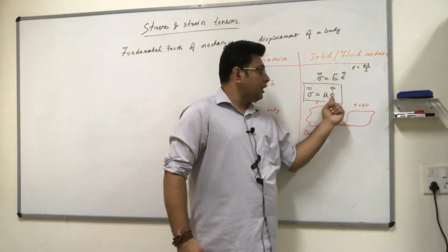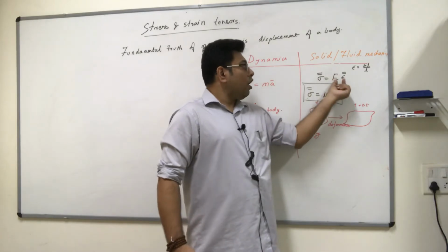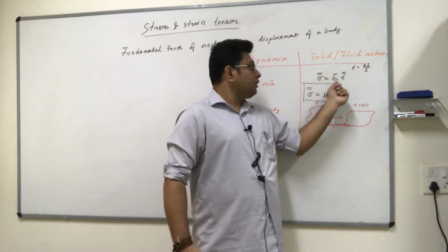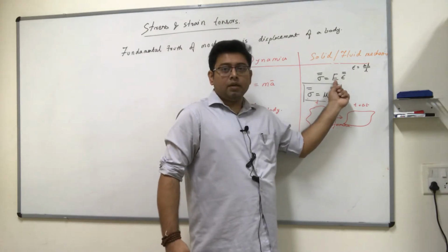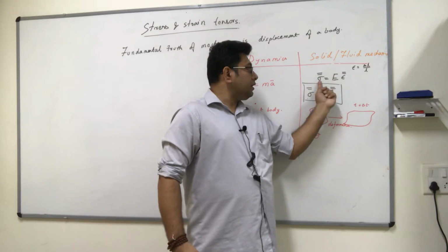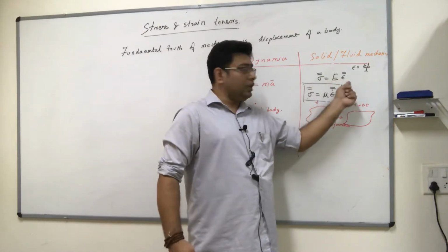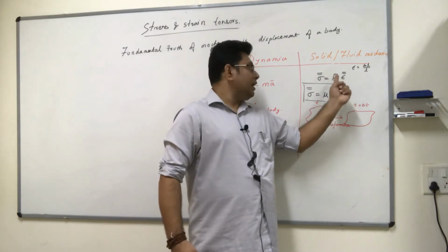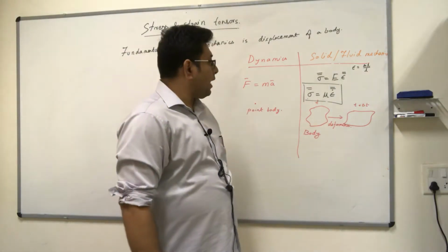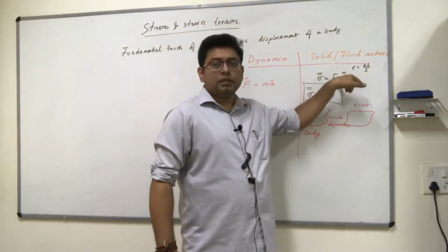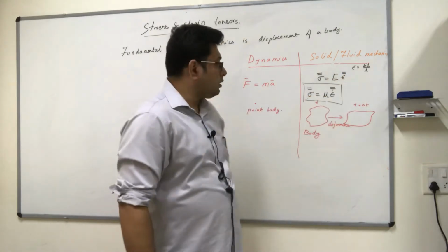And we will see that this actually becomes a tensor. This is also a tensor. In normal solid mechanics, this quantity E, which is a modulus, is a scalar, which it need not be. This is a tensor, this is a tensor. In the most generic case, this can be another tensor which relates two tensors, and then this becomes an even higher order tensor. It's called a 4 tensor in mechanics. But often, for isotropic cases, we can just think of it as a simple modulus.